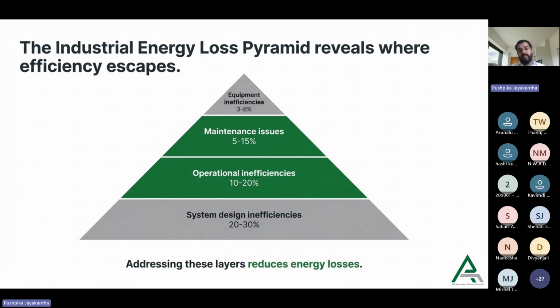So definitely you have to focus on maintenance scheduling and implement regular inspection of equipment, and the cleaning part. You have to establish cleaning procedures and checklists for equipment, and proper lubrication. You have to do those maintenance activities, otherwise the equipment will consume more energy.